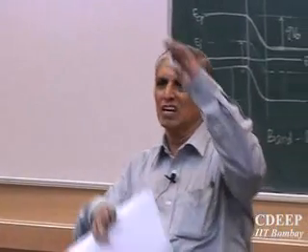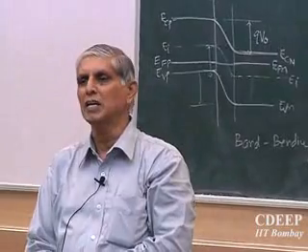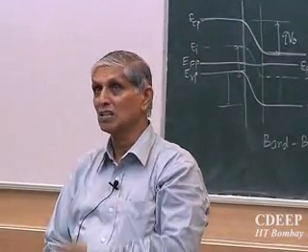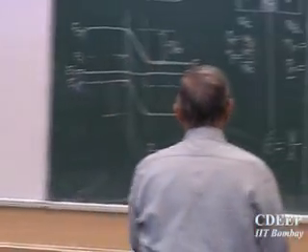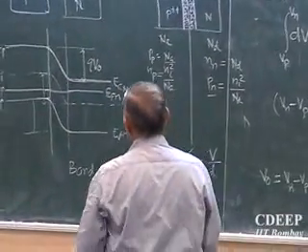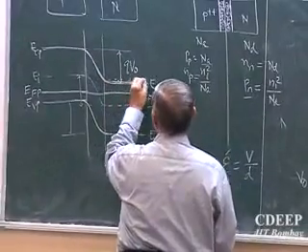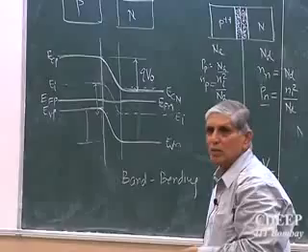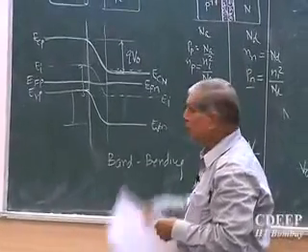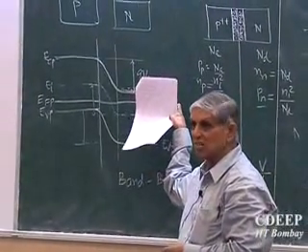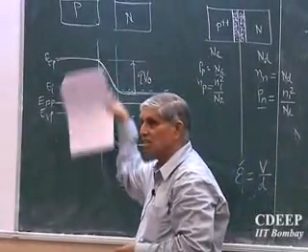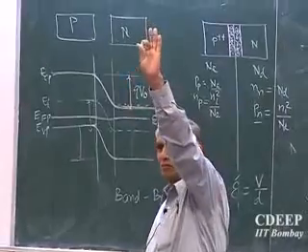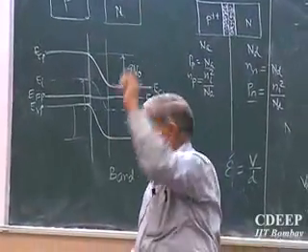So essentially there is an energy difference between N and P, Vn to Vp, and we say electrons are now... you can see why I was saying that further electrons couldn't go. So let's say there were a few electrons here. To go to the P side, what will they have to do? They must get at least this much additional energy to cross this. This is like a potential barrier problem. I have to climb. Is that clear?